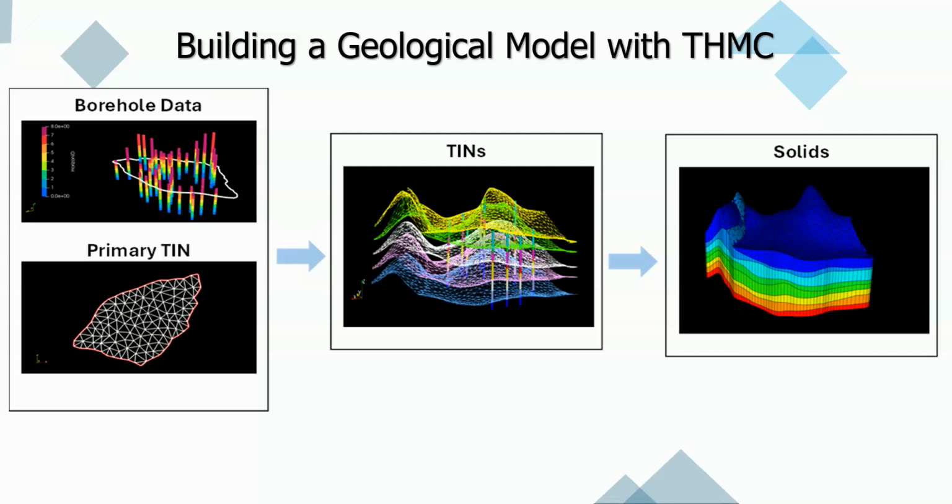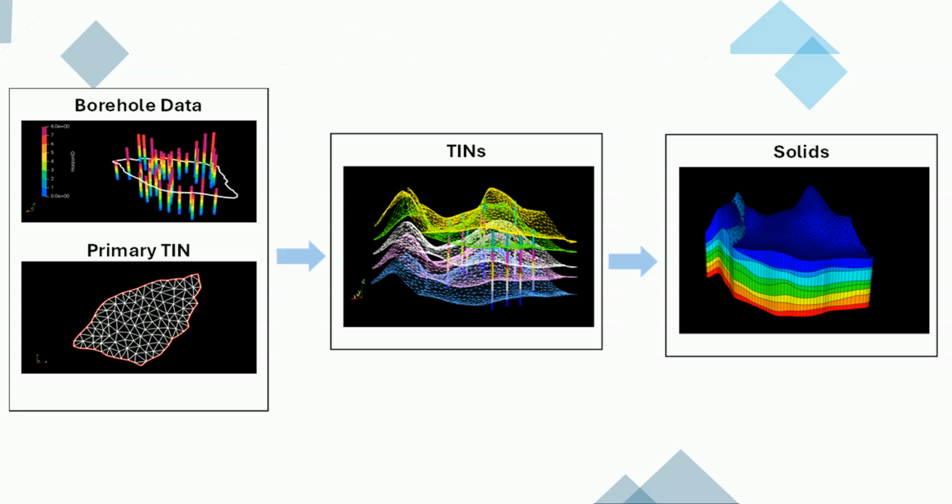In this video, we will introduce the fundamental concepts, operational procedures, and customizable features involved in constructing a geological model. The geological model demonstrated in this program is constructed using an algorithm proposed by Alan M. Lemon in 2003. The core concept involves importing borehole core data, then determining the depositional sequence of borehole materials to assign horizon IDs from the bottom up.